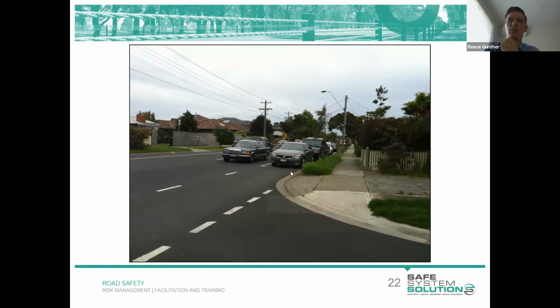Great answers, everyone. You've done really well there. There are two recommendations that were adopted: the timed zone and the curb build out. I think there are additional considerations to removing the tree if it was deemed possible. I know that councils are very sensitive about their trees, particularly around environmental issues. So trimming or removing that tree if practically possible, or simply banning the cars, maybe the first 2 cars, from parking at that location altogether, or removing that parking altogether. Fantastic. To the next slide.